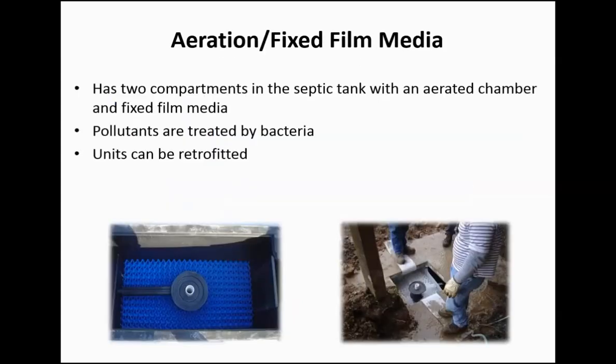This again is two compartments in the septic tank with an aerated chamber and a fixed film media. Pollutants are treated by bacteria, and the units can be retrofitted to prevent failures, increase the treatment values, protect the environment, and increase the property value.